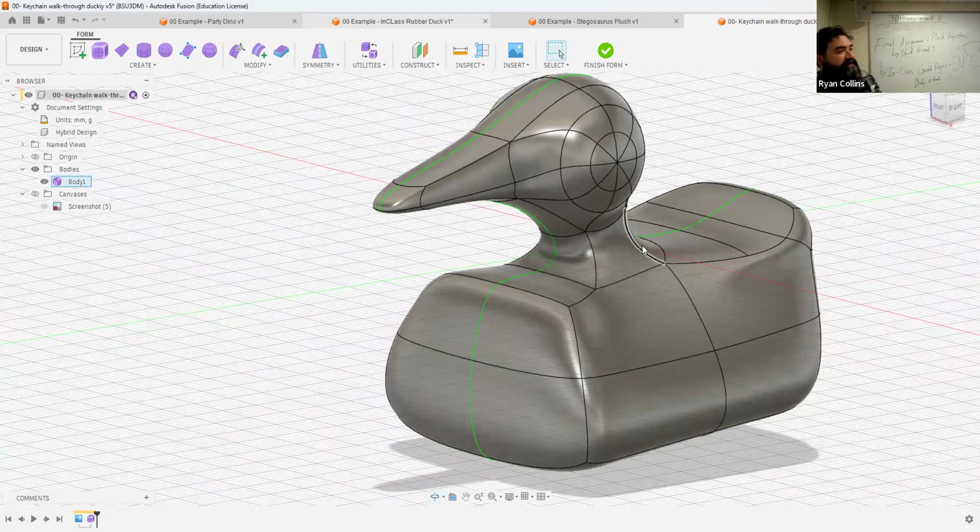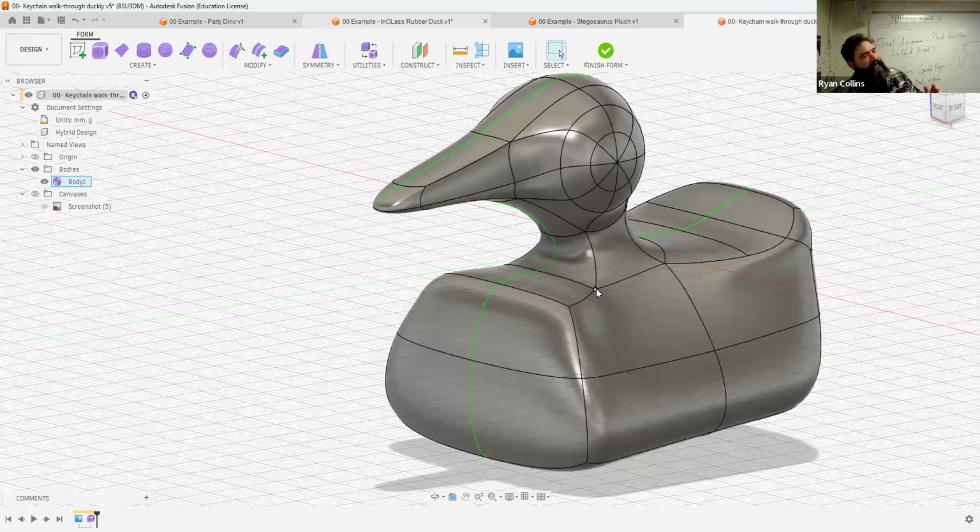So the main thing with this, the periodic to non-periodic error is usually because you have mirror or symmetry on one and not the other, or they don't match. But as long as they have the same number of faces on both sides, they can match. Well, what if I have too many on one and not the other?